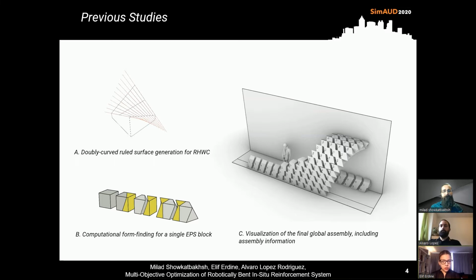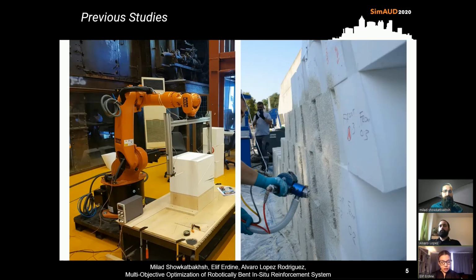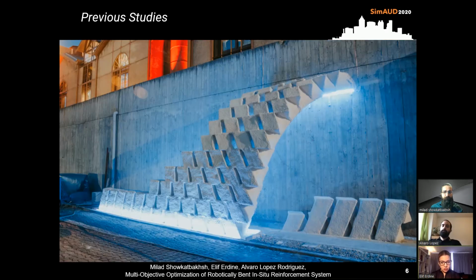This has been ongoing research for the past 2 years. Our research topic has been the development of formwork generation and concrete application for complex geometries. Particularly, our key consideration has been the reduction of formwork waste material. In this first iteration, a computational workflow for producing only positive elements from EPS as stay-in-place formwork was realized. This process was governed by the geometrical rules of robotic hot wire cutting. The stay-in-place formwork was later covered with GRC technology.